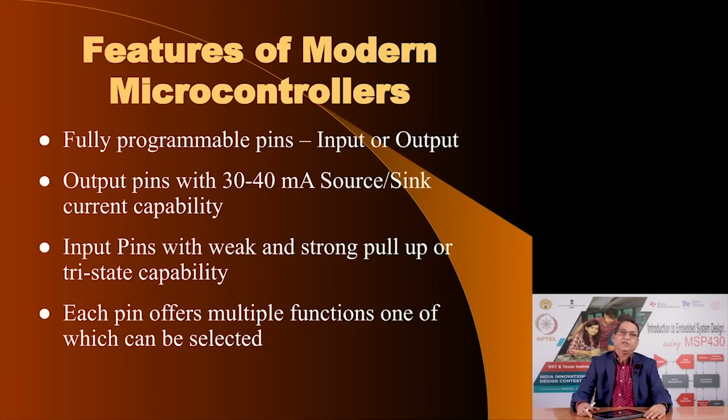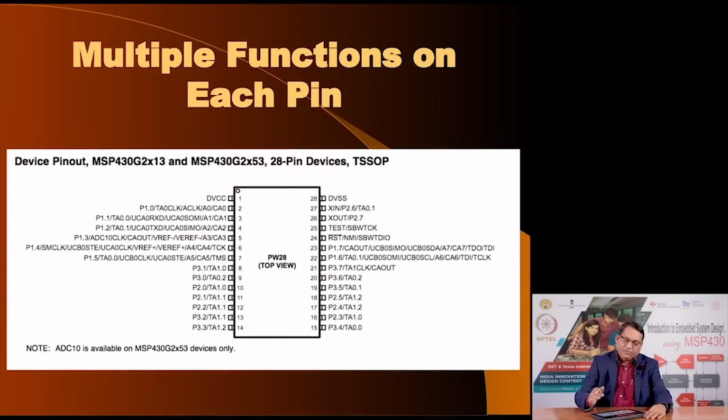Let us see what this means in a pin diagram from one of the MSP430 microcontrollers. Here, as you see, this is a 28 pin device. Pin number 1 and 28 are VCC pins. They do not have any other function, and rightly so. They are used to connect power supply voltages to this microcontroller.